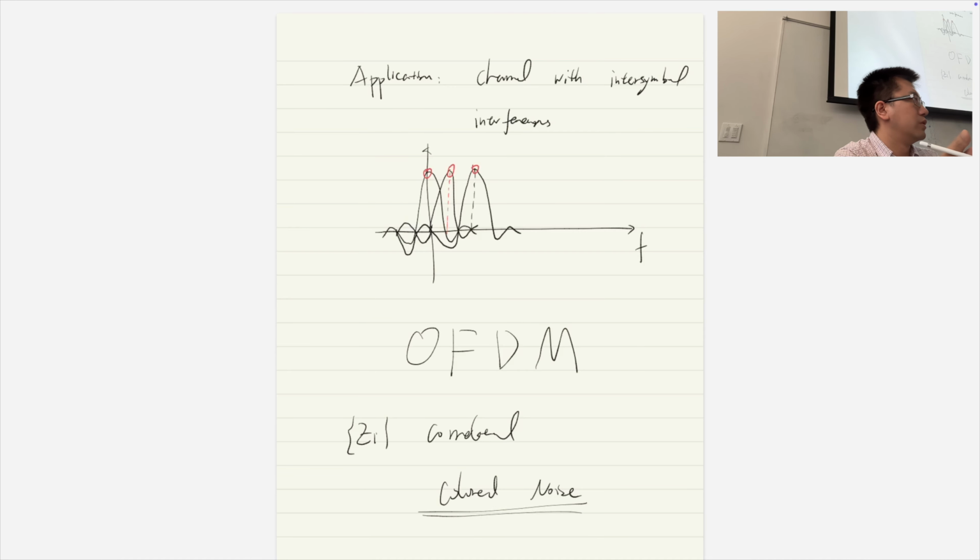In that case, what should we do? Let's say we transmit the signal via a constellation, and let's not consider channel coding. If we just transmit a signal via a constellation, then in practice we transmit complex numbers. Let's say we use QPSK, so we only transmit the signal over these 4 positions. Then we cannot use the capacity formula, because that needs a Gaussian input. Then can we still use the water filling principle?